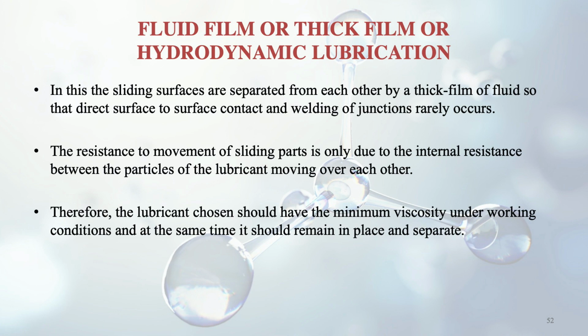And the lubricant chosen, that's why, should have the minimum viscosity, because if it is too viscous, then also the movement will be hindered under working conditions. And at the same time it should remain in place and separate. So two properties are needed: it has to be not very highly viscous, and it should also not be very light or very less viscous, such that the fluid flows away. So that should also not be the condition.